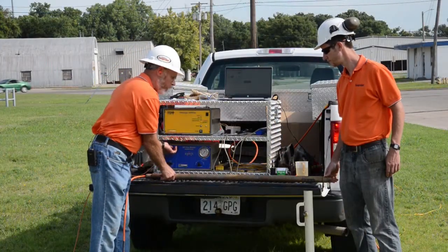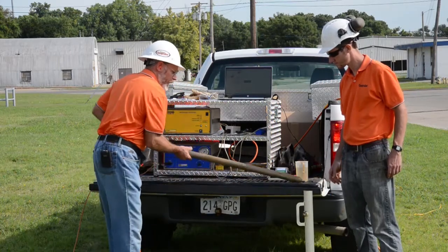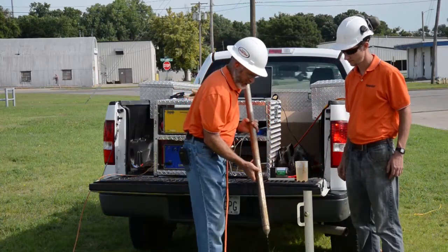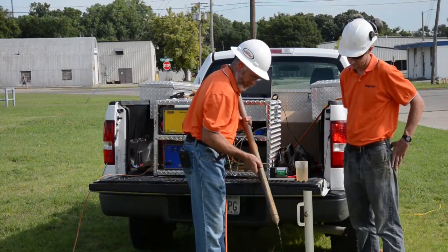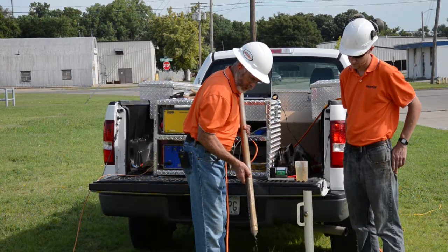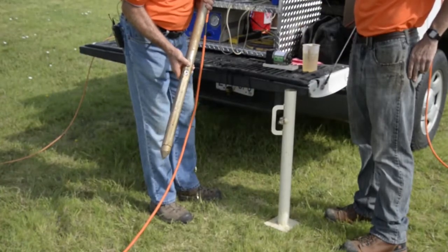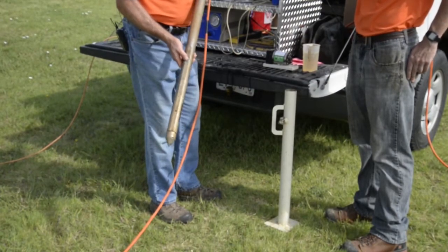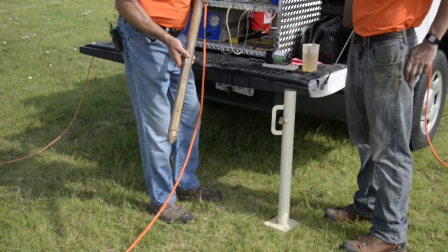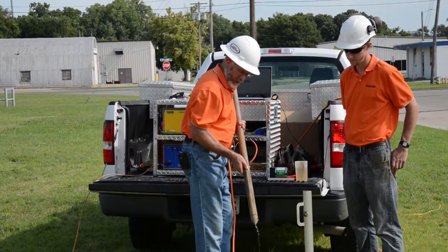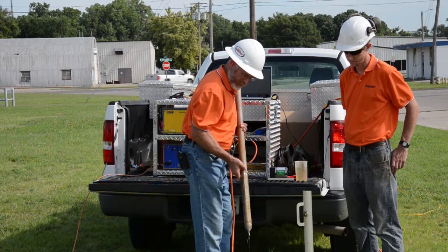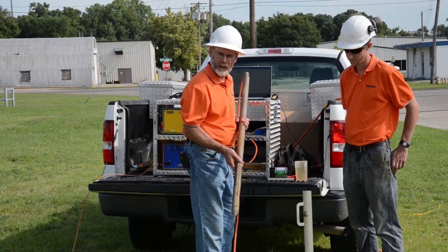We'll turn our flow on and let water start flowing out the screen. Okay, so you can see, maybe you can see that we have water flowing out the screen, and I'll put a little pressure on it and you can see the water kind of jet out. And usually we'll run the trunk line when we first start up a few minutes to let it purge air out of the system, and I kind of pressurize the screen 2 or 3 times during this process to help kind of burp the air bubbles out of the system here.